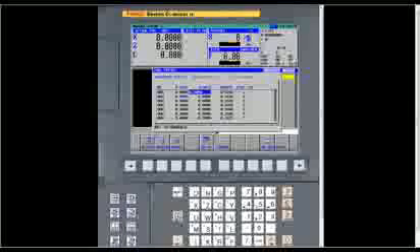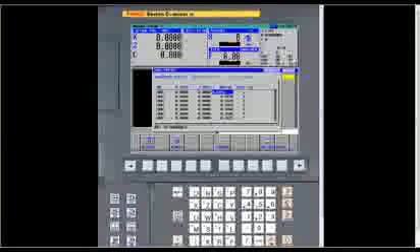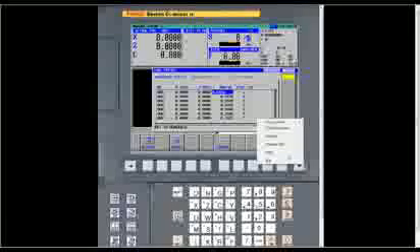Now we'll change the cursor as we page over. The next value that we need to fill out is the radius. What that's asking for on a turning tool is the radius of the actual insert. I know on my tool, this is an 80-degree left turning insert. I'm using a 31 thousandths nose radius tool. And where I get that number from, let's do this.